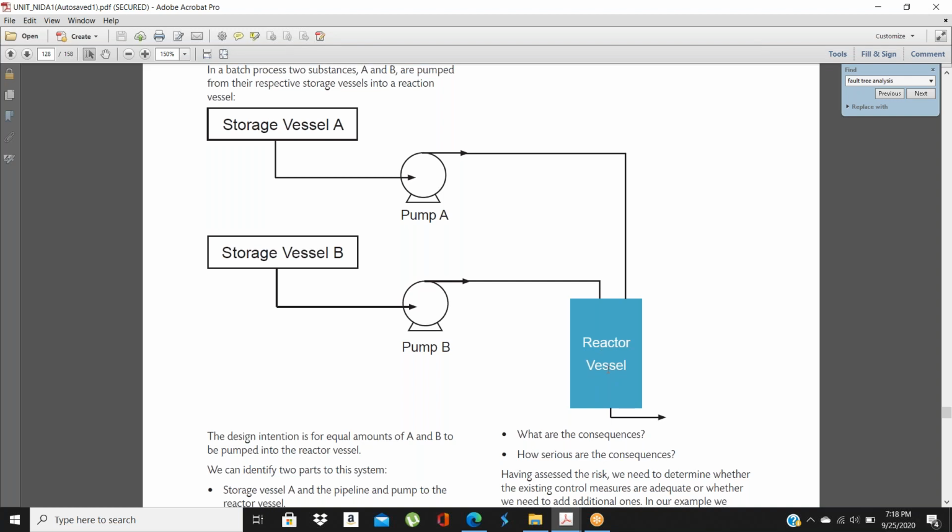Your reaction rate will become slow. So we need to install a temperature sensor here, and we need to install cooling jackets here. It will take the heat outside, and your reaction rate will become more. So now it's okay.